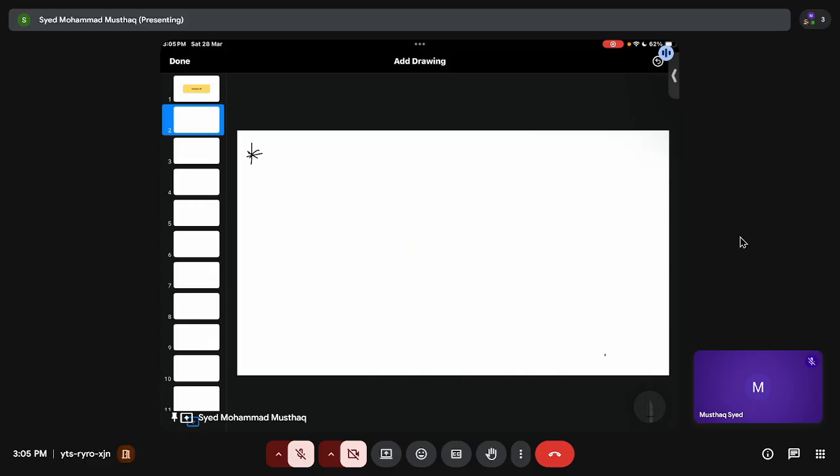Now, in this session, we will discuss the reduction of iron oxides, or the extraction of Fe from iron oxides, or hematite. The most common ore we see is hematite ore. Before going to the extraction, we need to know which is the best reducing agent. Most of the ores we get are in oxide form, or in some carbonate or fluoride forms, right? So mostly we deal with either sulfides or oxides. Iron is mostly available in oxide form as hematite ore, Fe2O3. So we need to reduce that to get elemental Fe.